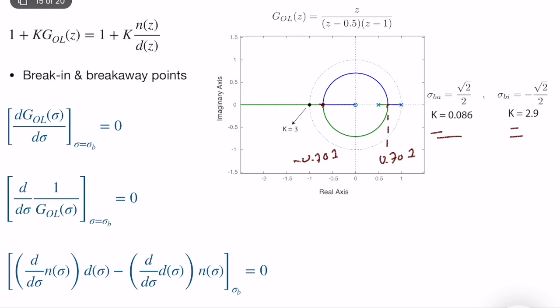This oscillation is different from the smooth continuous oscillations that we observe in continuous systems. These are more like tick-tock oscillations, because at some point it's positive, negative, positive, negative. They are extreme oscillations. It's one of the important things you should be careful about in discrete time systems: a discrete time system is non-oscillatory only if all of the poles are on the positive real axis.